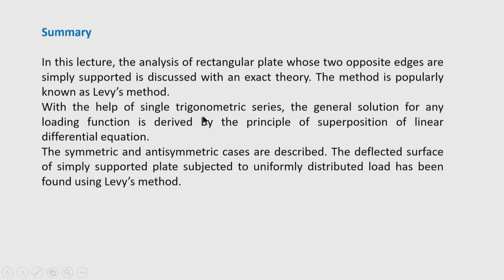I have told you that the best method to apply in the plate problem is the method of undetermined coefficients in the theory of non-homogeneous linear differential equations. The general solution is derived by the principle of superposition, that means the homogeneous solution is first obtained and the particular integral is added to get the complete solution. The constants of integration are evaluated by imposing the boundary conditions.